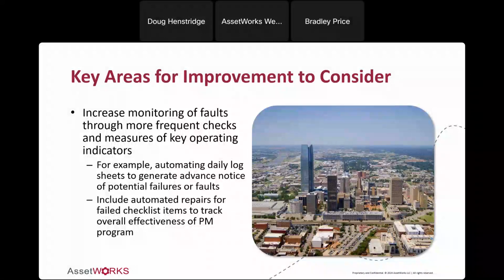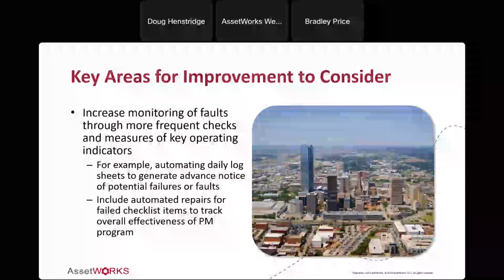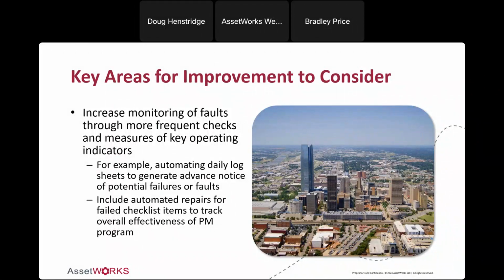They pointed out that even experienced technicians, when they do their boiler logs every day, will write numbers down, and without even thinking about it, they just fill the log sheet in, leave the clipboard, and walk off without realizing that the boiler temp was either too high or too low, because they got into a mode of, I just need to record this information and move on, right? And it's not that they're doing a bad job. It's just they're so overworked elsewhere. They're just noting the values and not realizing that may be an indication of a bigger problem.